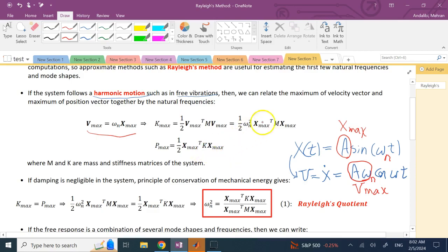So the case that we are looking at is no damping. We just want to find omega n, not like in vibration where we had omega d, if you remember the damped natural frequency, which was omega n times the square root of 1 minus zeta squared. So we are right now after omega n.